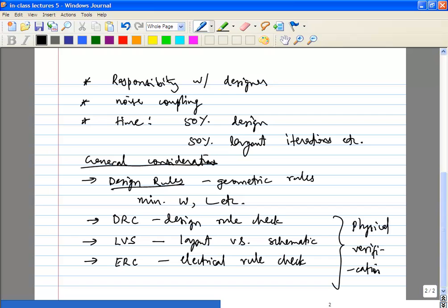Okay, so for example, let's say a lot of modern analog processes or even digital processes have two power supplies. So they'll have what is called a thin oxide transistor. So if you take a 65 nanometer process, for example, or a 130 nanometer process, you'll have a transistor whose minimum length is 130 nanometers and its gate oxide thickness is a certain amount, and you'll also have what are called IO transistors. Okay, those will typically be larger. So the minimum length on those may be, let's say, 0.25 microns, 250 nanometers, and the corresponding oxide width will be thicker. Okay, corresponding voltage supply will be higher for those transistors. For the 0.13 micron transistor, we are using 1.2 volts. The other one may be, let's say, 2.5 volts or 2 volts.